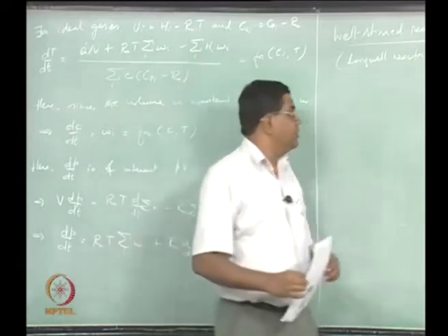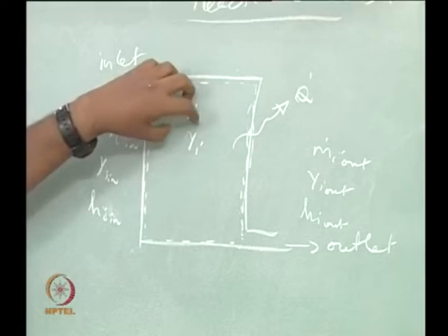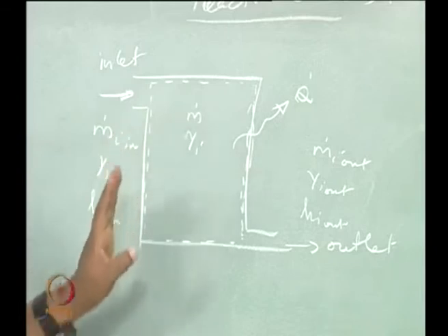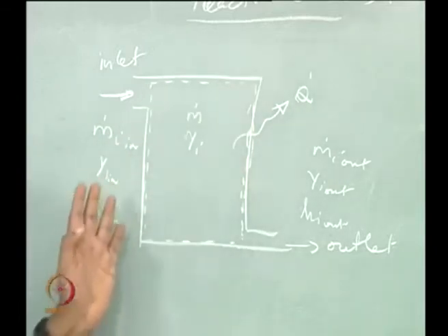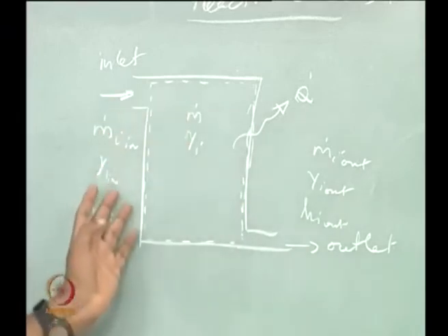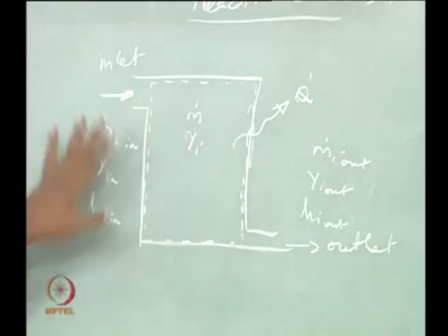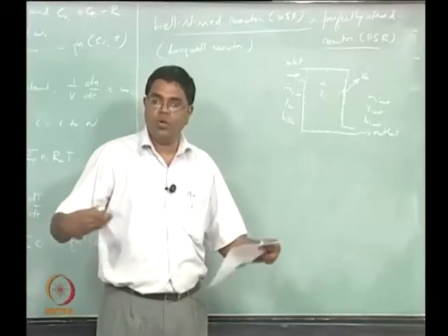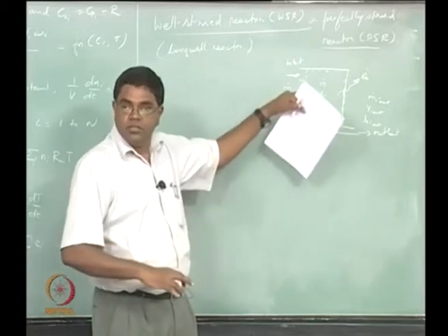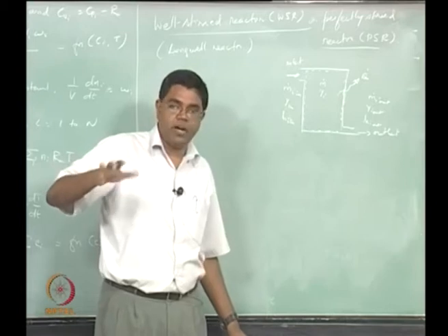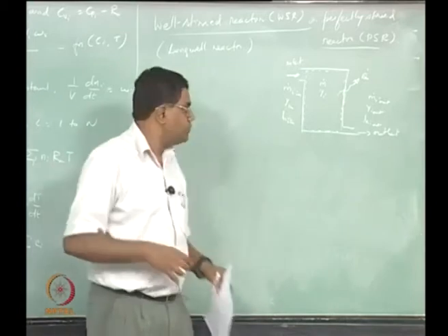What parameters? Typically we are looking at what is the size of the reactor that you want to work with, and what is the heat out that you want to get out of this reactor. So depending upon these and the input conditions, you will get the corresponding output, or you will now get the composition inside the reactor and the temperature to attain based on what is the size at which you want to operate this reactor. Size is given by m dot, that is like the throughput, and what is the heat that you want to get out of this. So these are now like the key parameters in the problem.